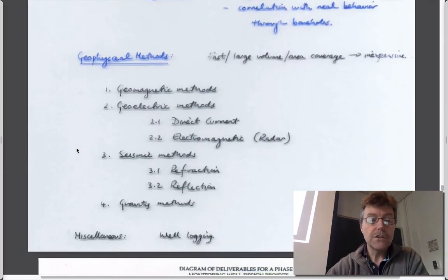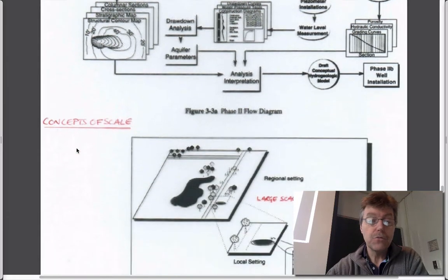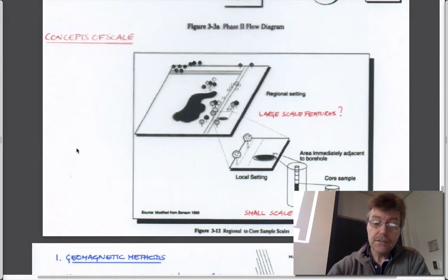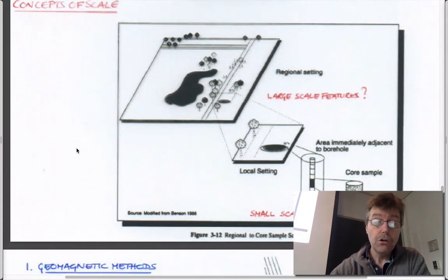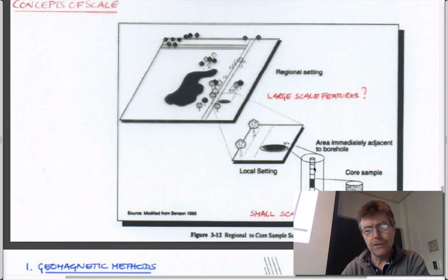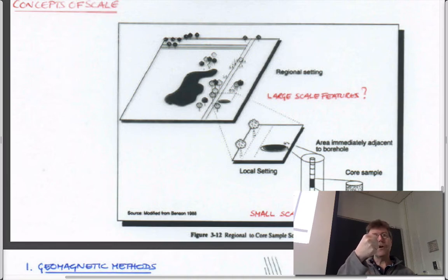And so typically the way that it's used in these different workflows, and actually this isn't a bad figure to illustrate it, is you have a drill hole somewhere. So this is a plume on the edge of a lake, and at the edge of the plume you have a drill hole, and from that drill hole you have a core. So you could calculate exactly what the volume ratio of this core is relative to your site. Probably not very much, probably a millionth, something like that. But what you do is that on these places where you have drill holes, you have very accurate information and samples that really tell you what exactly is there and has some physical meaning to what you might want to know. Permeabilities, porosities, entry pressures.